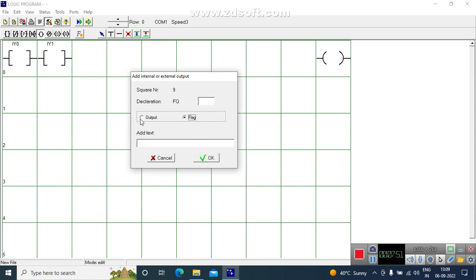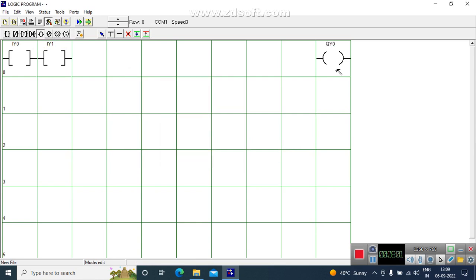Well, let's now talk about only input output. So I connect an output. Okay, output, as I said, is 0 to 31, that's 32. So we take output 0. Now what this output does, physically when you connect it to the PLC, this will drive a solenoid or any electrical output device. This is nothing but a relay contact output. So contact will close and open depending on the logic.